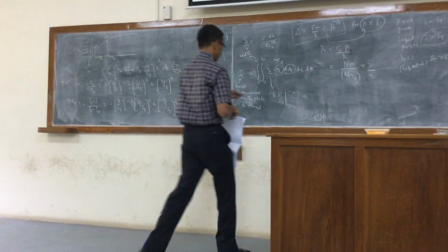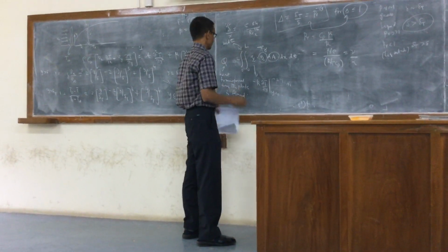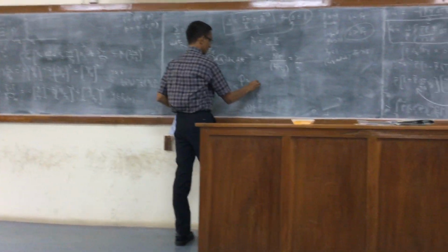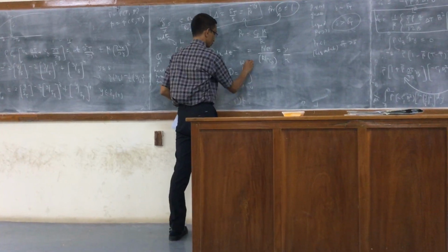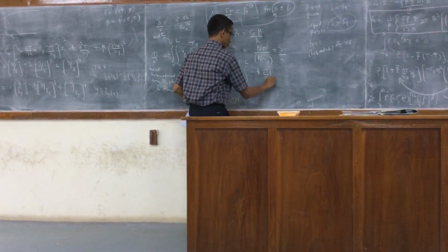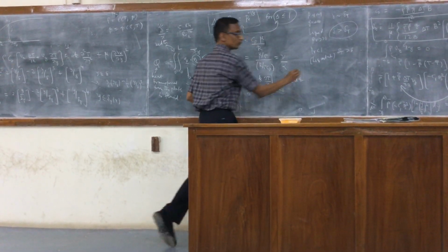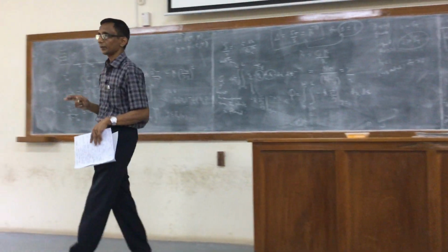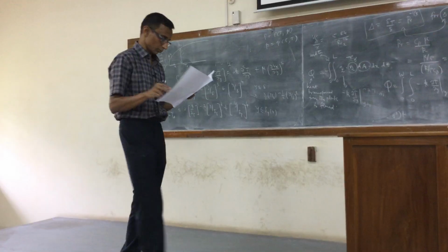So that negative sign will finally remain because this is going to cancel with this. So I can write Q itself as the integral 0 to w, 0 to L of minus k dT by dy at y equal to 0 dx dz. You have to be able to write these unambiguously so that you don't